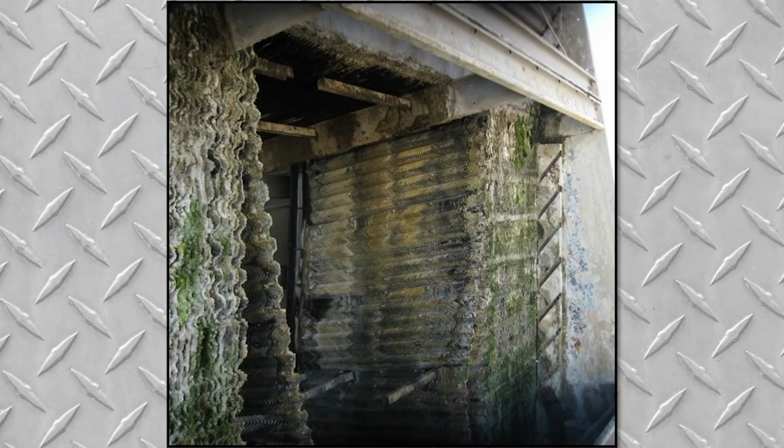Now, cooling towers tend to exist outside and usually outside the view of management. We find roofs and cooling towers to be places where there's usually maintenance issues. And there can be some pretty ugly things, like what's shown in this picture. The fill here is all moldy, and as the mold gets on there, the heat transfer of the surface greatly decreases, hurting the performance of the cooling tower. We see lots of leakage, damaged fill, broken access doors, and much more.